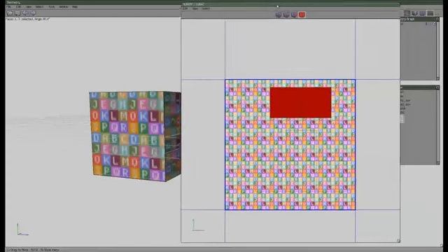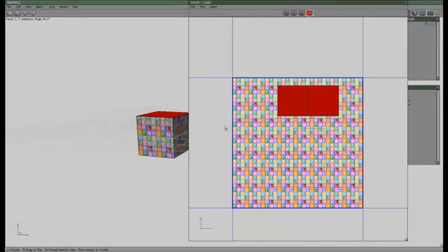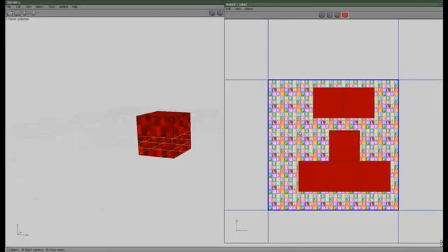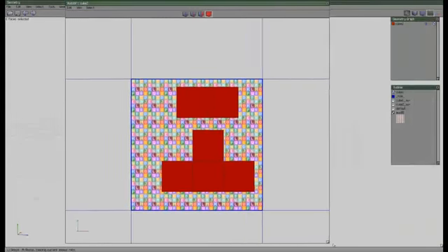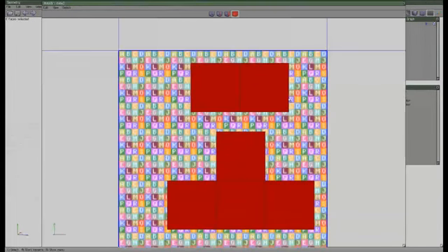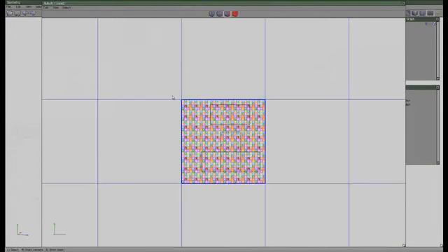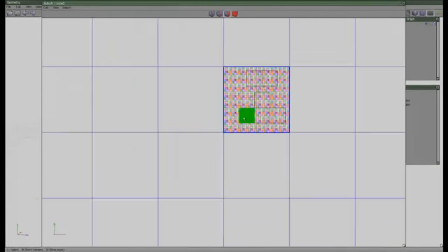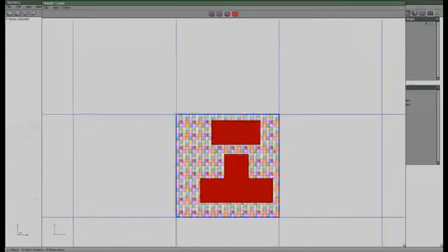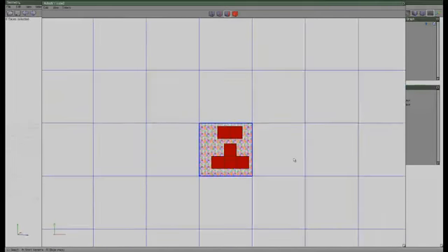So let's talk a little bit about the controls in here. What happens in the UV mapping window, the 3D one, is quite simple. Just right-click menu, and the controls are the same. But then once you unfold or project or whatever you want to do, you get this actual 2D UV mapping screen. And here the controls are just a little bit different. So again, you can zoom in on your selection by pressing A or Q, depending on your keyboard. So it's just the first letter on your keyboard. You can zoom in on a selection. Scrolling is just the middle mouse button scroll.